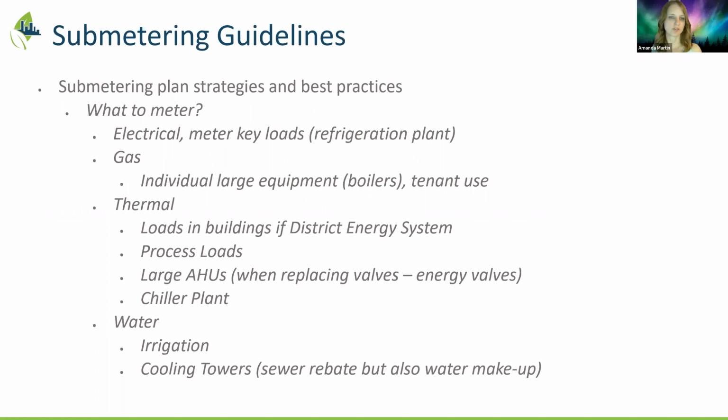And then, as I alluded to earlier, we've also added submetering systems on larger energy saving retrofit projects so we could complete M&V. Typically, if the load isn't dispersed across the building, but we're targeting a specific asset, then we can add a meter to it. If it's a whole recommissioning where it touched everything all across the building, then we would use the interval meters.